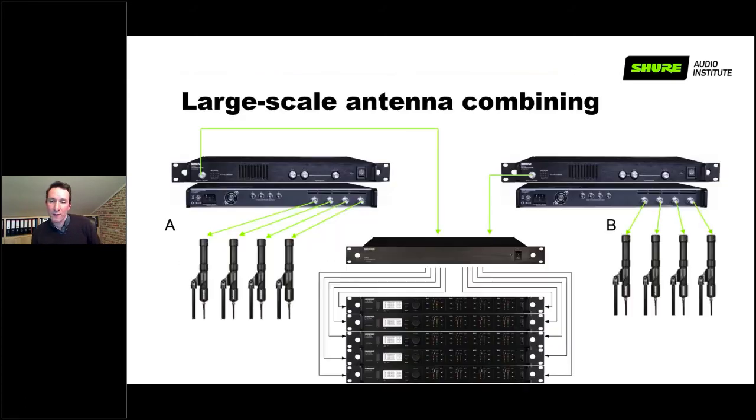If we look at the schematic, on the left here we've got a 4-way antenna combiner that gets the signal off of 4 antennas, combines it into one output, and then feeds that signal into a distribution unit. And on the right, we do exactly the same thing for the B side. So this active unit would replace the whole diagram of bias Ts and passive splitters and everything that we had in there with a single unit.